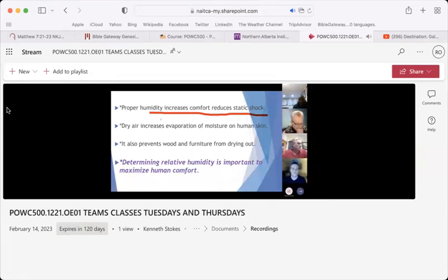And I think between ventilation and humidification, those are the top 2 items that are important. If the air is dry, if we use steam especially and or hot water heating, we're not normally circulating air, so we're not doing ventilation, and we're definitely not doing humidification, or usually not other than spot areas. And buildings like that can be very, very uncomfortable.